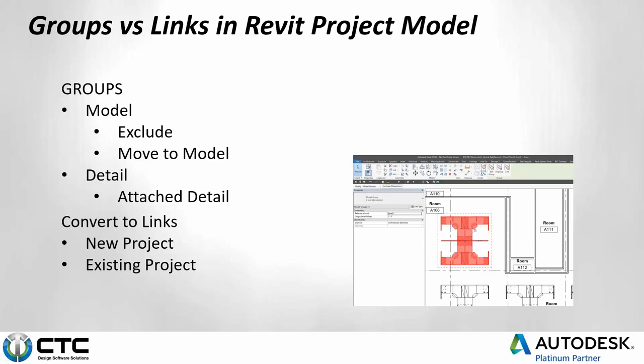And with attached detail group, these are tied to a model group. So they're kind of one and the same with a model group, but they're classified slightly different than just a detail group. Detail groups are placed by themselves and they're only 2D objects, whereas attached detail groups are a detail of the model group that you may, when you're selecting the objects, you may have some documentation stuff on that